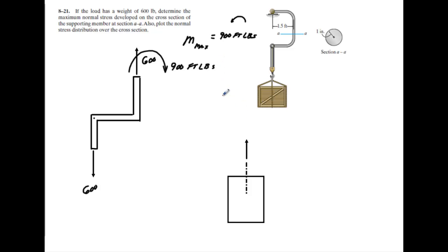Okay, so now I've taken an area right in here, and I'm showing it right down this view right here. So at this point, you would have 600 coming down, or sorry, 600 coming up. This is creating a moment that's bending it back this direction. So obviously this beam is going to have to resist that moment.